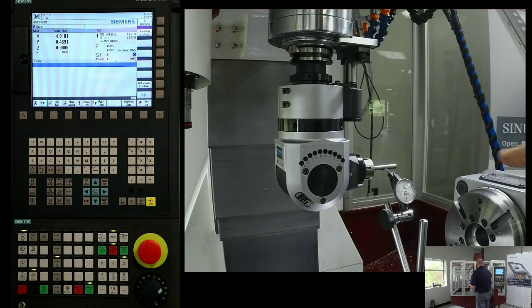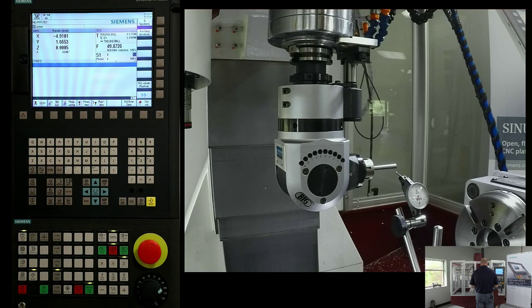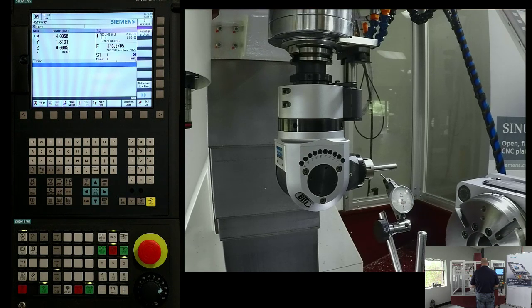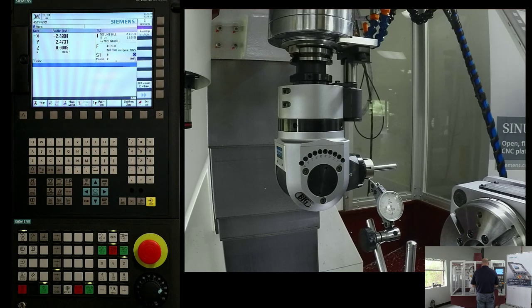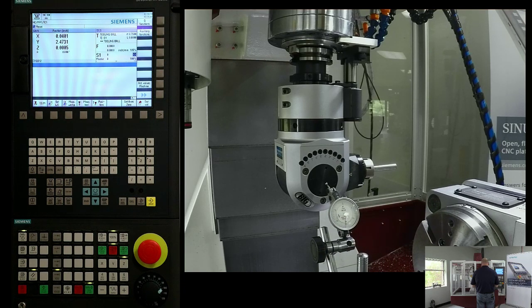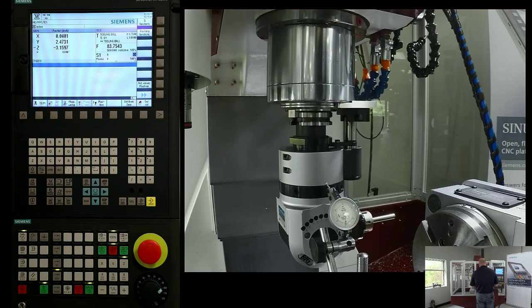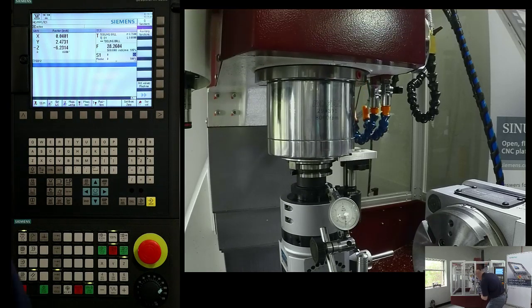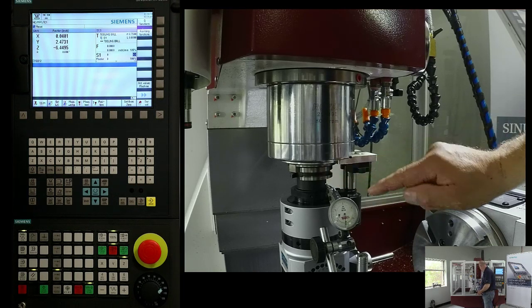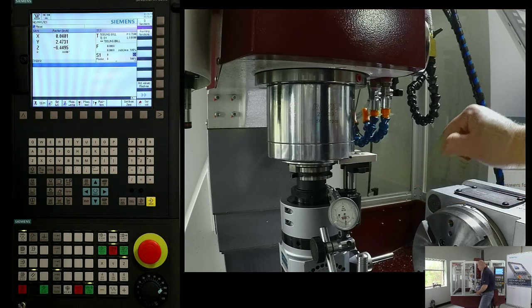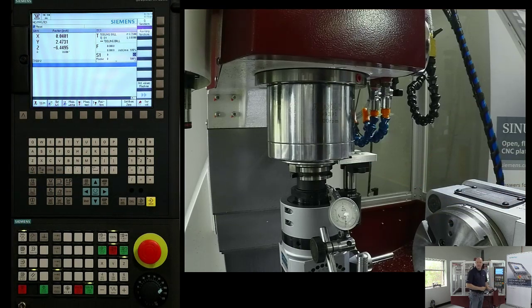Now then what I have to do is measure from center line to my gauge point. So really what I would do is remove the head, but for time's sake, I'm just going to give you a quick demonstration of what I'm talking about. Imagine the head was physically removed right now. I would bring my indicator over. I would bring my head down, right? And I bring it all the way down until my indicator physically hits my spindle face or my gauge line. And I would run it until I'm sitting at 0. And now the distance on my display would be the distance from gauge line to center of rotation.